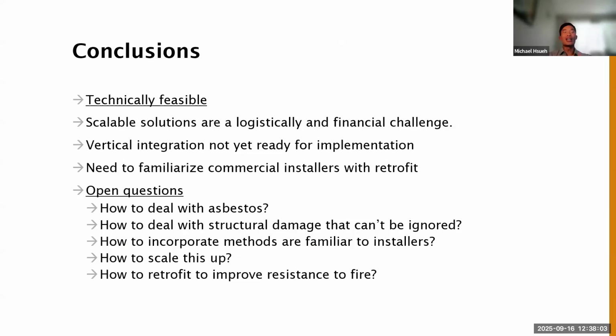So my conclusions from doing these retrofit demonstrations is that they're technically feasible, but we ran into some significant logistical and financial challenges. It cost a lot more than we wanted, which is why I was pointing out that there's a whole mix of strategies that we did. We were fixing the existing walls, bringing them up to a better standard. We installed these panels, we installed new windows, we did the air sealing of the attic. Things like the air sealing of the attic, I think, were very good targets for further retrofit efforts in the future.